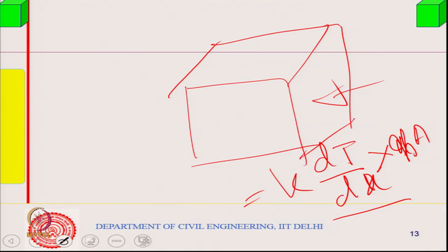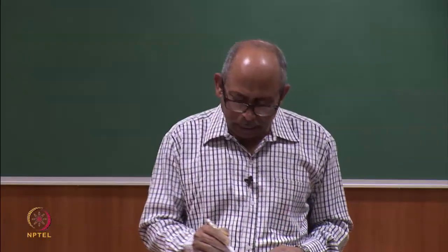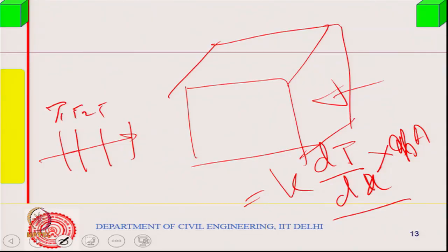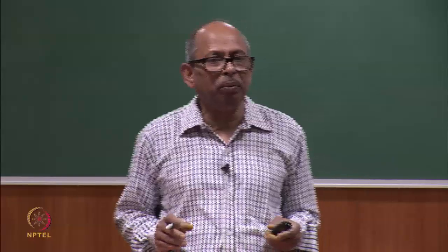So, that is the amount of heat, but then you have a layered system. Did I discuss this sometime earlier in this class? Maybe not. If you have a layered system, then under steady condition we assume the flow is the same, but temperature would be varying, T1, T2, T3, T4, etc. And if two walls are in parallel, subjected to the same temperature difference, then heat flow will be the sum total of the heat flows, like series and parallel models.